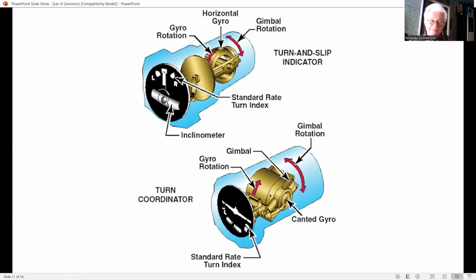First condition, A, vulnerability to damage on the ground or bird strikes in flight, as the sensors have to be mounted externally on the aircraft. B, problems in matching due to the differences in the local airflow at the different locations. So like two sensors located on the port side of the fuselage and two sensors on the starboard side.